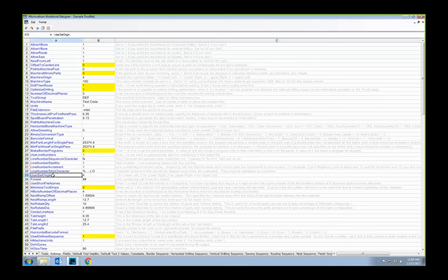You can fill out this information, but this really is just for your information in column A. All we're looking for in the program is a number in this column. So if you do the route and you notice the trim cut is not in the right area and there is something here, then you can play with those numbers until you get it to shift around to where you want it to be, and it will work just fine.